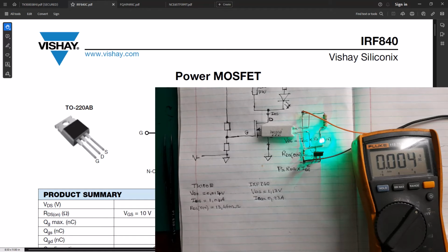So we can go ahead and calculate our RDS on for this MOSFET. Let's turn this off. Basically with these parameters, we found the value of RDS on equal to 1.18 ohm. That is very close, slightly high, because as we know, it's specified at VGS equal to 10 volts. If we fully turn this IRF MOSFET on, we should be getting a value closer to 0.85.